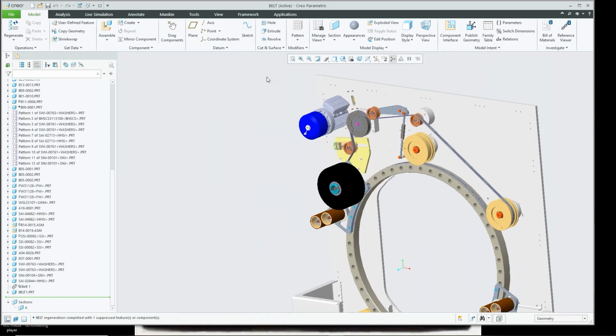So once again, with that one, we have all of our pulleys and all of our items in the appropriate location. We just need to connect them with a belt loop. So we go through and define the actual belt using the mechanism tool. And then once we're done, if we need the representation of it, we can have it. But also remember, the benefit of this belt loop is that it actually goes in and gives us the actual length of that belt as well.